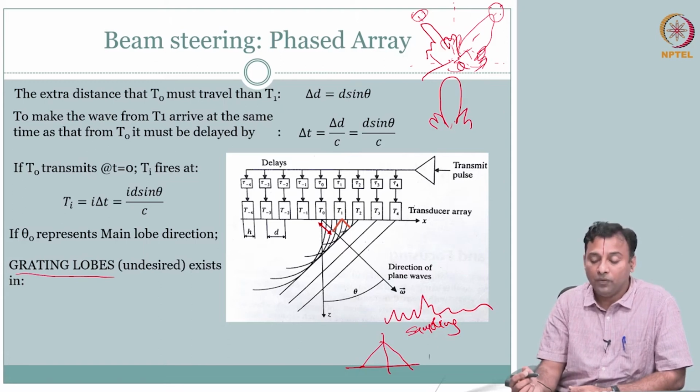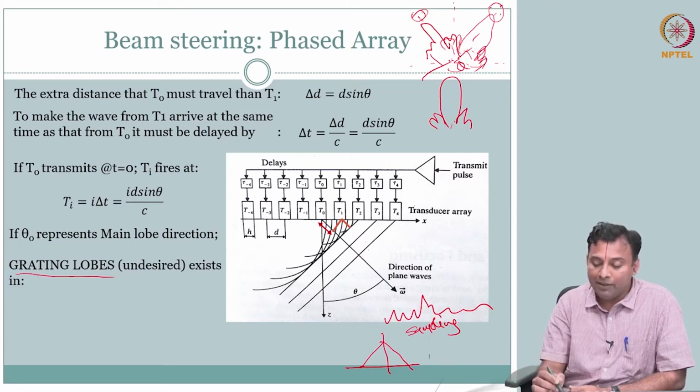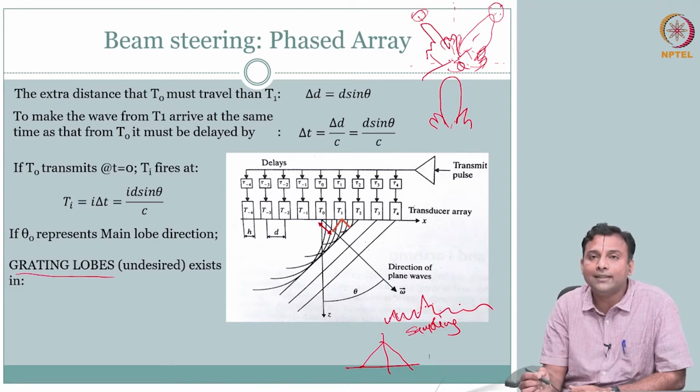Oh, now this is a time signal. If I sample it, how fast do I have to sample it? Oh, I have to sample it at least twice the highest frequency. If this is the spectra, I have some highest frequency, and I will have to sample at least twice that highest frequency. Then, this is the continuous time spectra, FFT.